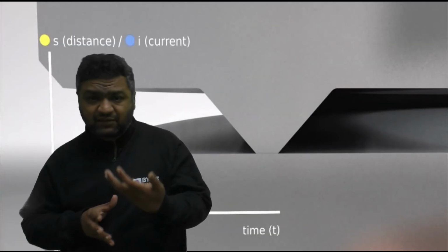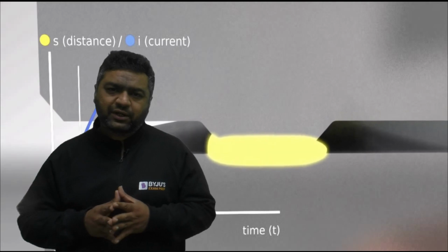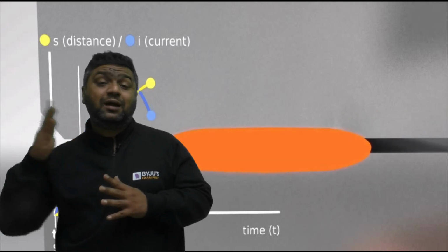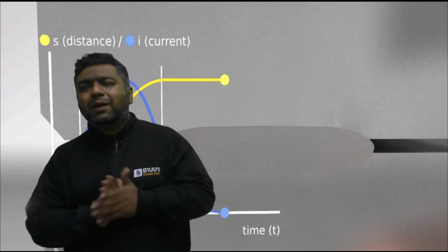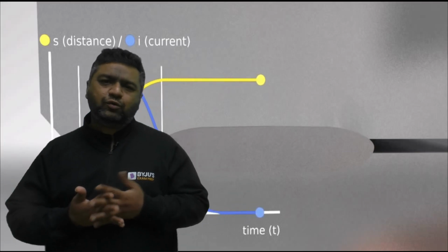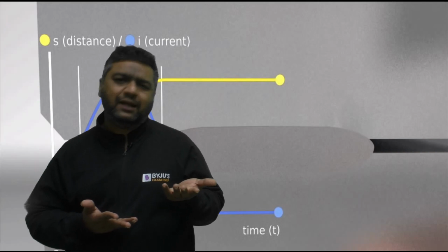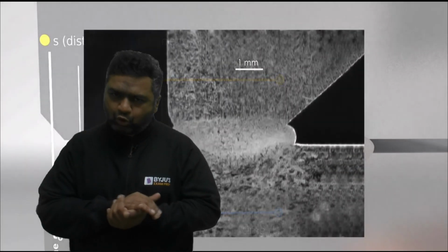As I already told you, while selecting the plate with the projections, because of plastic deformation, more heat is generated. So selection should be either with more thickness or with more conductivity. Now, when we are talking about multi-spot welding, it is just similar to spot welding, but here we are making multiple spots.